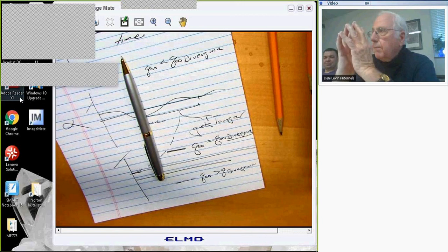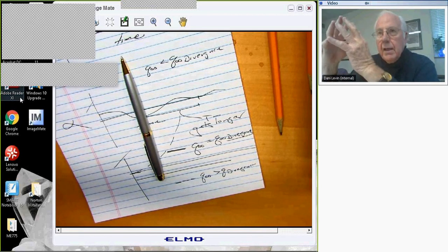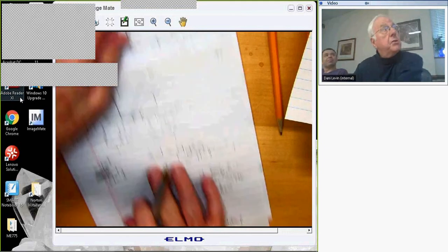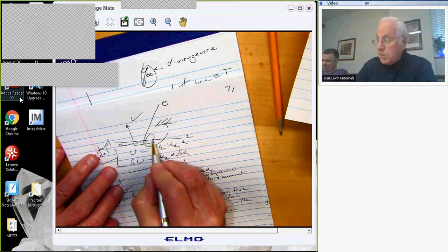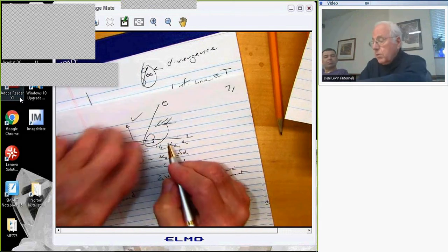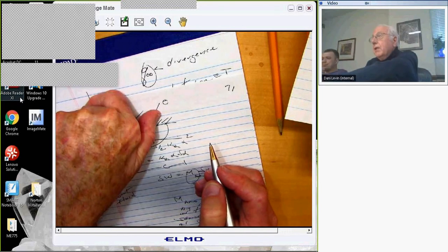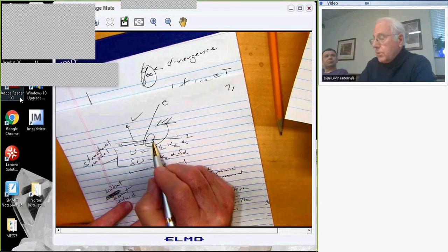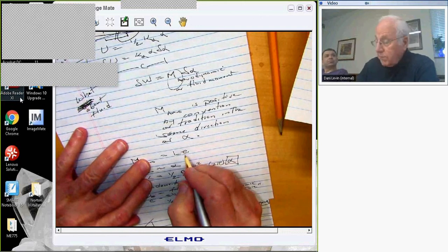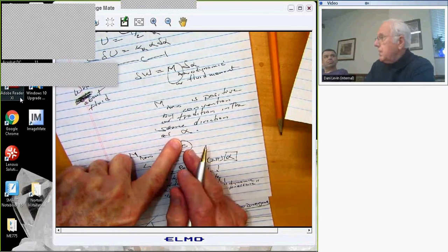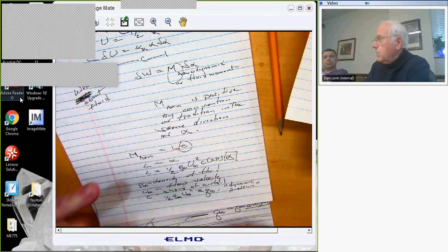Now, as to why the aerodynamic forces can do that, it's really a matter of where the lift force is placed. Let me go back to my picture here. If you remember this picture, I cleverly put the lift force ahead of this point for the spring to be connected. If this lift force were behind this spring, when this flexes upward, the lift force would actually create a moment pushing back down. And you never get divergence if the center of lift is behind the spring point, which in the aeroelastic literature is called the elastic axis. And that deals with the sign of this distance, E, right? I define E as positive when lift is ahead of the spring connection point, but if E were behind, so that E was negative, if this point were behind the elastic axis and E were negative, then I would never get divergence. Okay? Now, that's one answer.